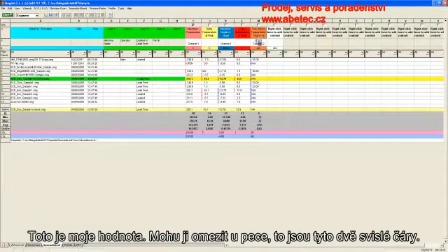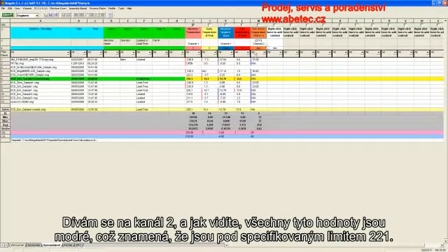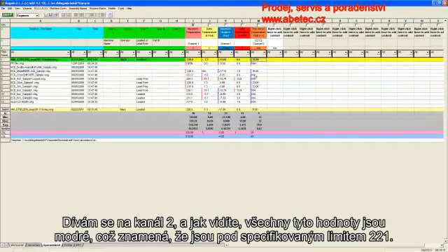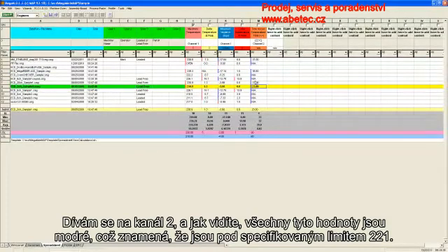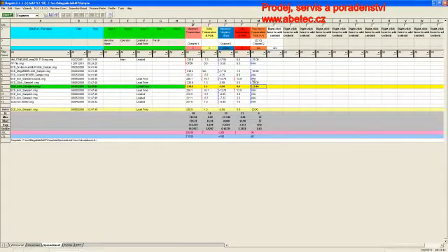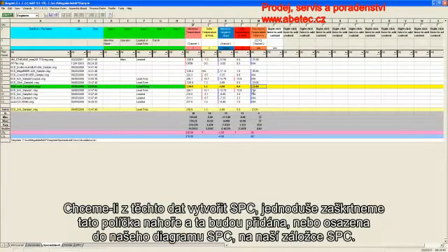So here is my value. I've constrained it between the oven. That's what these two vertical lines represent. Our time above temperature is 221C. I'm looking at channel 2, and you can see that all of these values are blue, meaning they are below my specified limit of 221. I'm sorry, below my specified limit of 60 seconds. So they have a blue bar to the left of them.